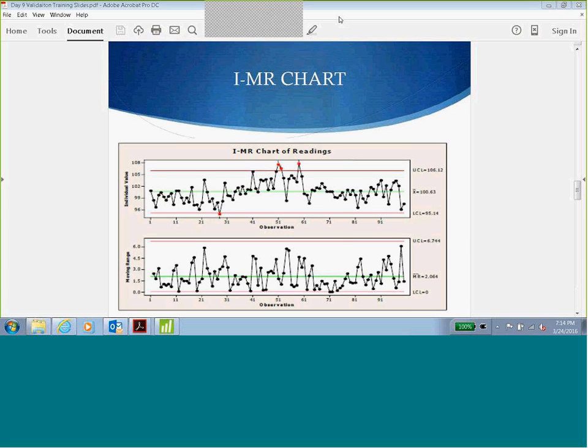and sharing. So you have 100 samples. Change the values of the samples, with some samples close to the limit and some samples away from the specification limit, so that you will get a PPK value less than 1. If your measurement results are outside the specification limit, then obviously your CPK is going to be less than 1. Then play around with the next set of data where all the samples are close to the target, and you will get a good CPK value, in this case greater than 1.